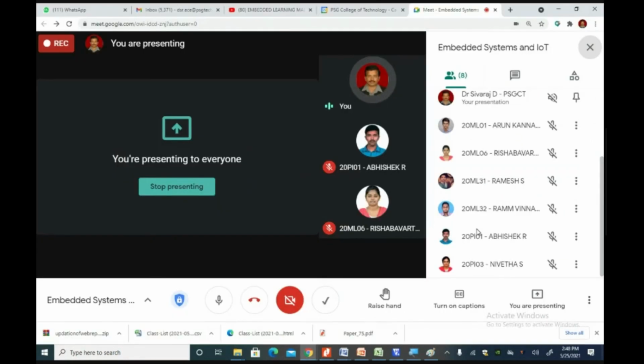So these capture modules are very much useful in finding the speed of the vehicle, right? If there is a speedometer in a car, speedometer in a bike, you say that 20 kilometer per hour or 40 kilometer per hour or 80 kilometer per hour. If there is a digital display, those digital displays are happening only by measuring the pulses coming from the wheel speed sensor. Okay. All the speedometers, all the RPM of a motor speed control, and wherever there is a speed measurement or tachometer, whatever you call, all are measuring the transition between the rising edge and falling edge, which is on time. Based on that, they will measure the period, and by measuring the period, they will find out the frequency, and they'll say this is the RPM of the motor, or this is the RPM of the wheel. Based on that, they will compute the speed of the vehicle, and you can say your vehicle is traveling at 80 km per hour or 90 km per hour.